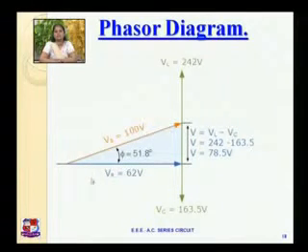So voltage across resistance is always in phase, and there is the voltage due to inductive and capacitive element. As we know, the inductive element is higher than capacitive element, so it is in upward direction. If Vc is greater than VL, then it is in downward direction. As shown in diagram, this is our VL 242, this is our Vc 163. So VL minus Vc, so your voltage is always in an upward direction. So this is an inductive circuit, so this is our lagging angle.